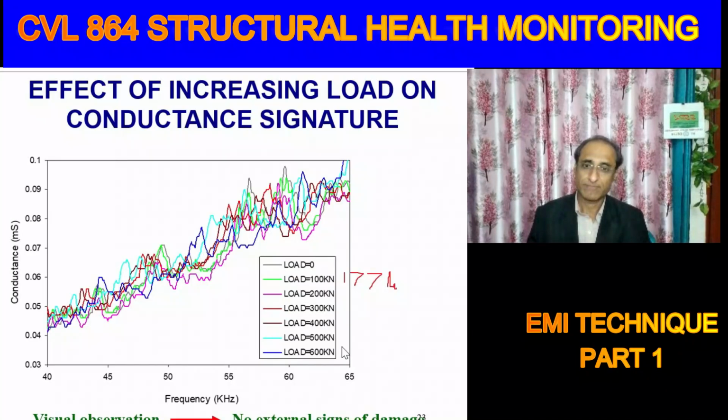Can you tell again? 1062 microstrain. So 1062 means about 1000 microns. Alright. How much is the compressive strength of concrete in terms of strain? Ultimate 0.003. In microstrains it will be 3000, exactly. So our strain level is quite less than that, right? But of course, this is a very crude estimation. Our strain level is much lower than that.